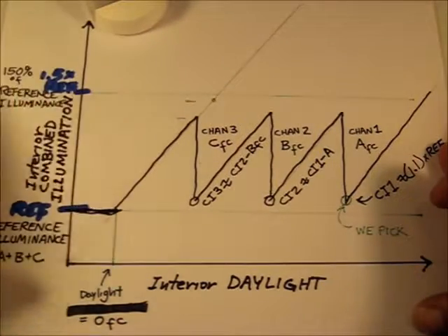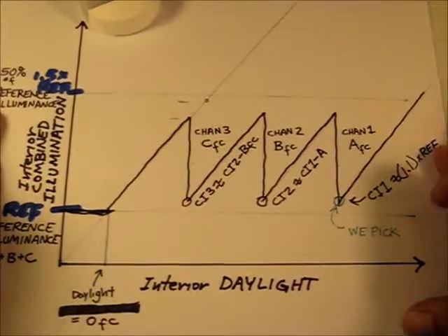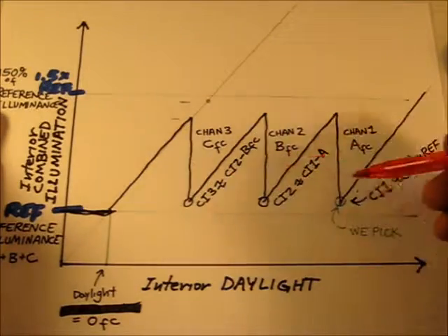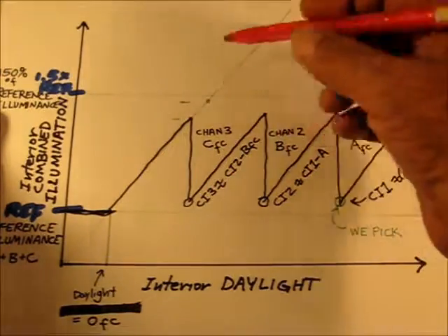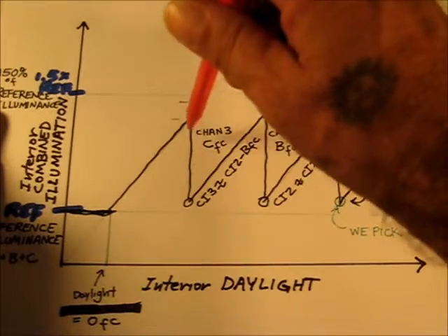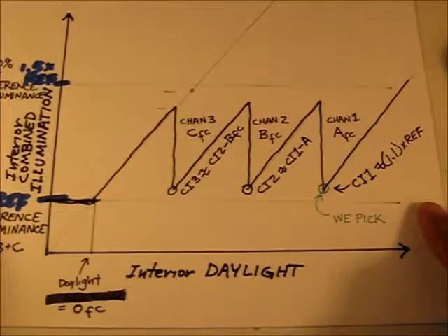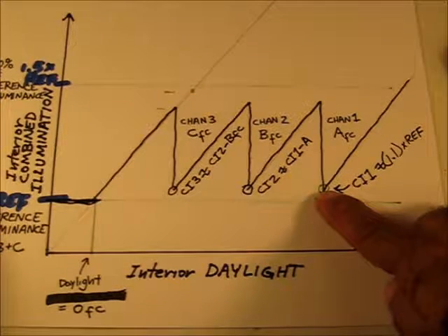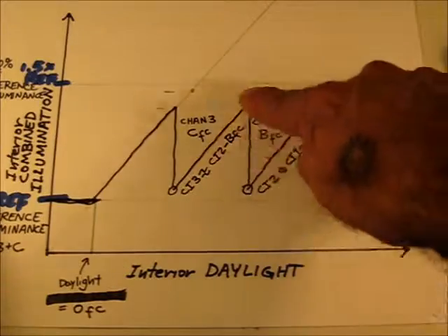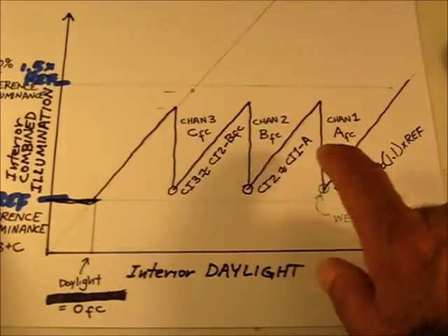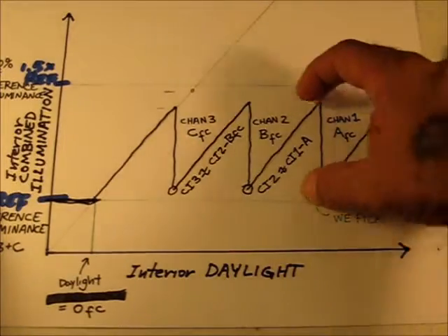And because our deadband in this particular controller for this particular system is based on the cut-in values, the deadbands will probably be different for each stage of lighting. Okay, now do recall that we picked this first point and all this stuff was based on it. Now we're going to base our deadband on these points and these measurements.